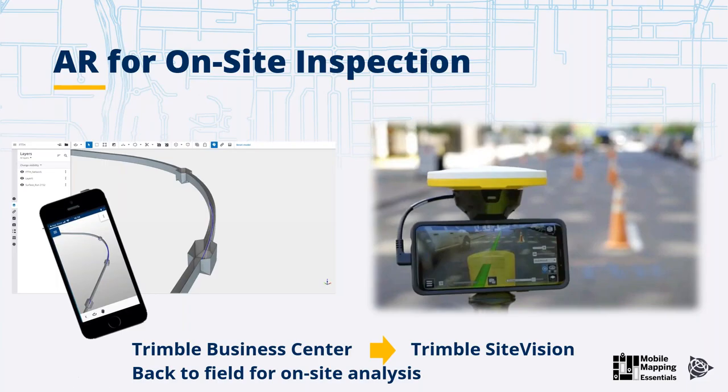a smartphone. So it's subscription based, the service which we provide. Together, of course, you need to bring your own smartphone, and we provide you this kind of holder, which also contains this GNSS antenna. Then the application can get connected to an internet RTK service provider, for example, a VRS network or single base, based on NTRIP technology. Then you can receive real-time corrections.